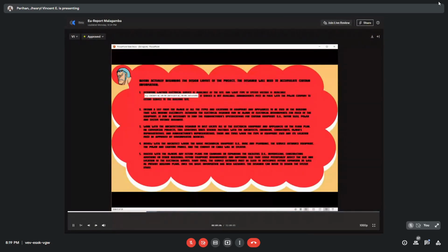So first is to determine whether electrical service is available at the site, and what type of system voltage is available, for example, 120 over 240 volts AC. If service is not available, arrangements must be made with the power company to extend service to the building site.